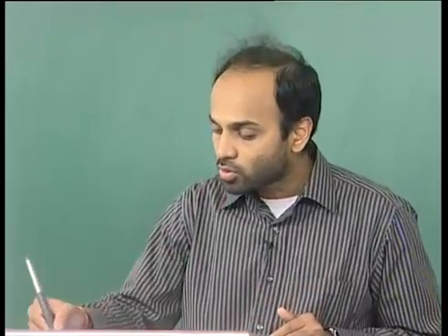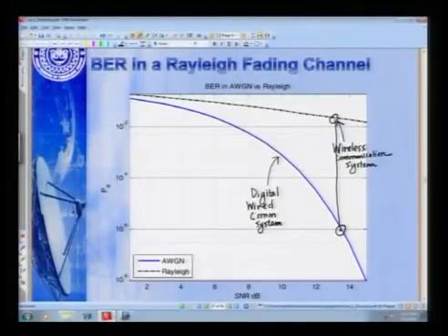communication system. So, that is essentially an idea, and look at how slowly this is decreasing with respect to SNR compared to the wired communication system, which decreases to 10 power minus 8 bit error rate at almost 14 dB. But at 14 dB, look at how high the bit error rate of a wireless communication system is. It is still greater than 10 power minus 2.